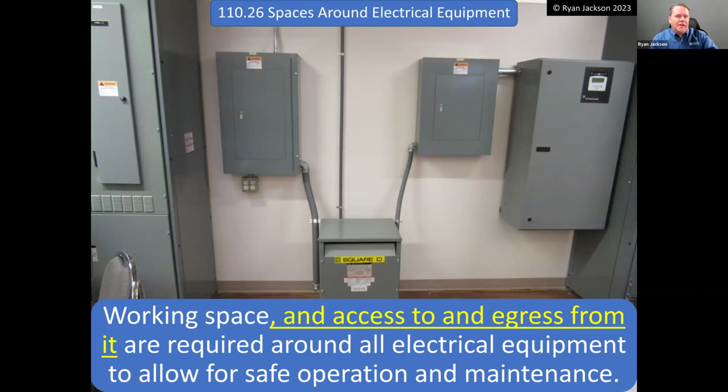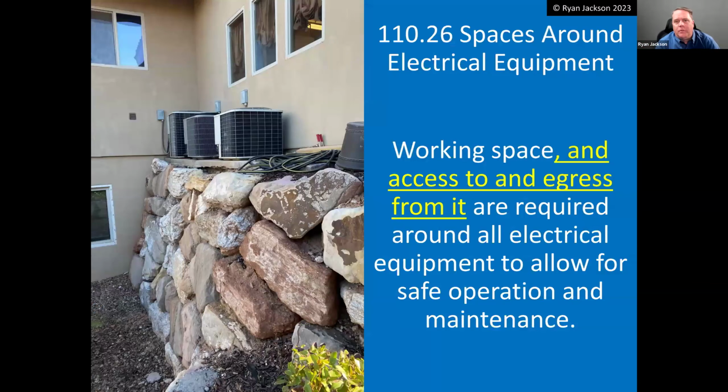because what's a transformer, right? If I were to say, okay, you need 3 feet in front of a transformer. Well, maybe we're talking about a transformer like the one in the bottom of this photograph. Or are we talking about one of the great big green ones out in the parking lot? Or are we talking about a doorbell transformer, right? That's in your house. So I can't say you need 3 feet in front of a transformer, because what's a transformer, right? So what this ultimately says is, listen, everything has to be capable of being worked on safely. That is a rule that stands on its own.